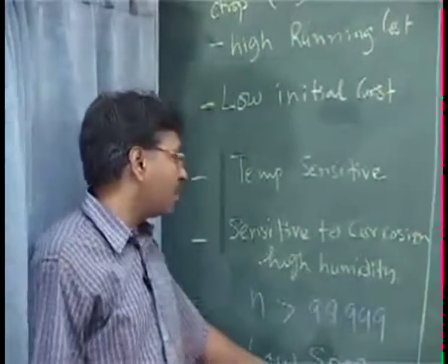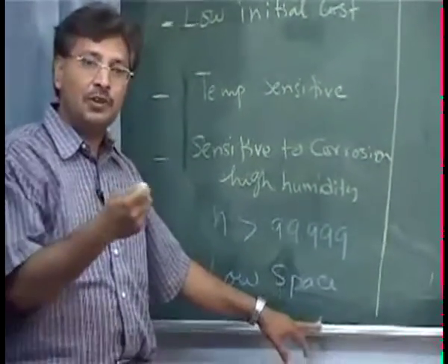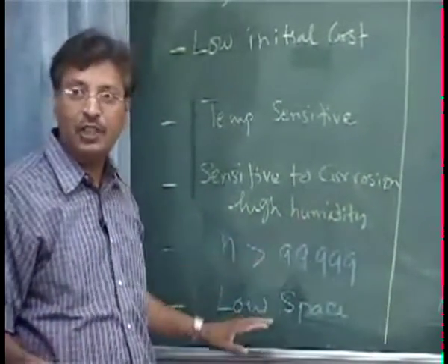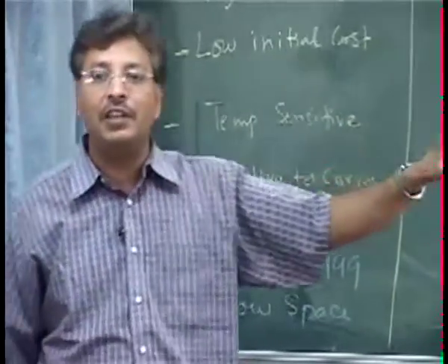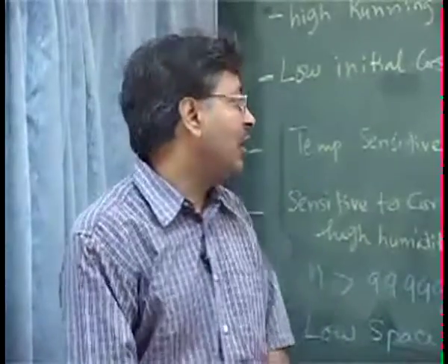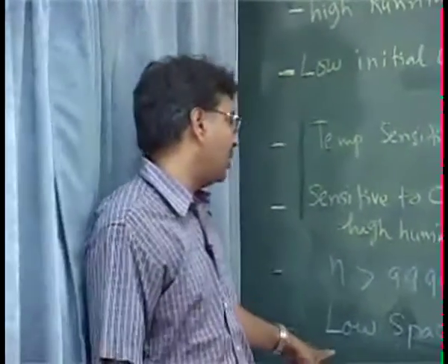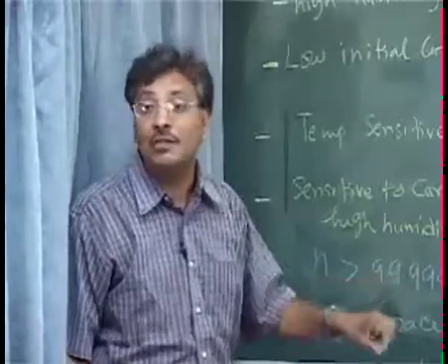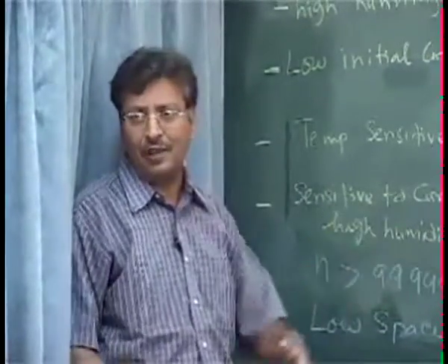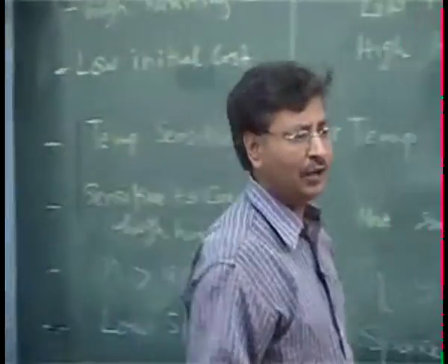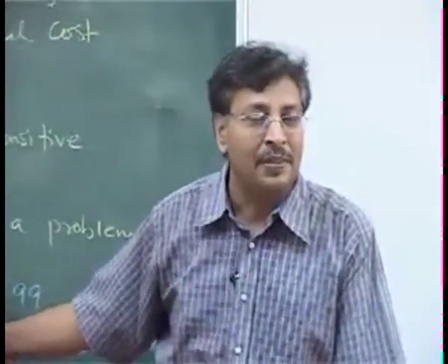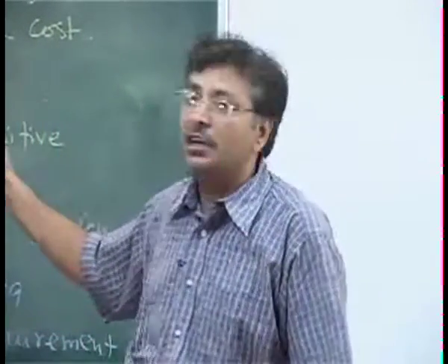If the gases are combustible or an explosion is possible because of the nature of the gases, you will not go for ESP. You will always go for the bag filter, because there is no possibility of any chemical reaction happening inside the bag filter. So that is another thing. People dealing with a process where the CO level is very high, hydrocarbon is very high, okay, then they will not go for ESP. There is a fear of some fire, but nothing to fear if you are dealing with inert dust like ash. So all the power plants in India have the ESP.